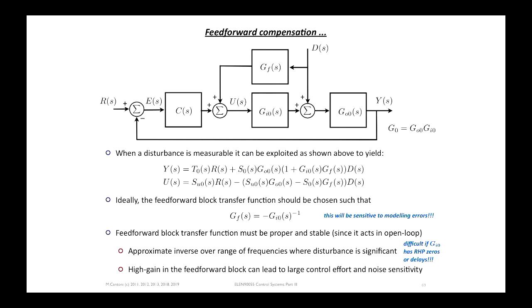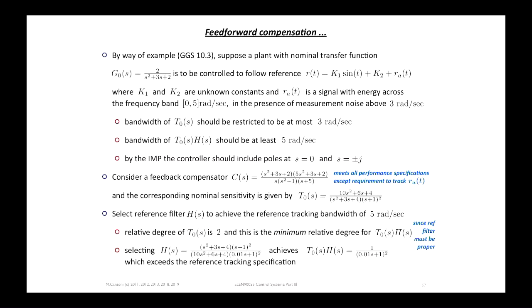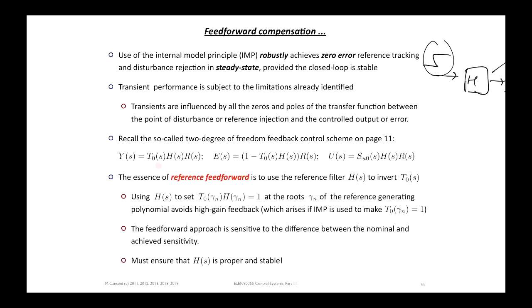But what we're doing here is not just inverting an open loop model, we're inverting things that, well, in this case we are, but in this case we're inverting a closed loop model. And part of the reason for closing the loop around a model is to make the closed loop less sensitive to modelling error, right?